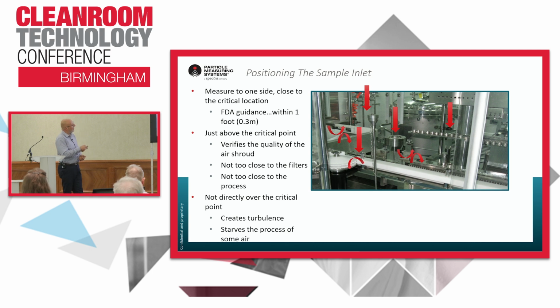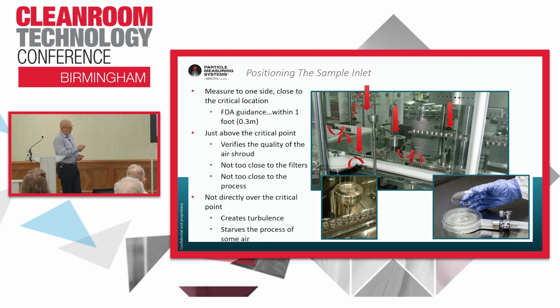That's the isokinetic for the non-viable sampling. Typically it'd be a bit higher up, and there's the viable sampling collection head that would have the plate inside there. And then again an overview of that at the side of a line next to some vials, slightly above it, or the single-use technology that can replace that with a slightly different style of bracket.